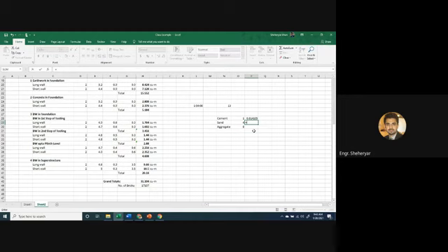Similarly, you have 4 parts out of 13 parts sand, and the total quantity of concrete is 5.184, and the factor for converting the wet quantity into dry quantity, since sand is also taken dry, is to multiply by 1.54. This is the volume of sand. Similarly, the aggregate is 8 parts out of 13 parts. Multiply it with the volume of concrete, which is 5.184, and multiply it with the factor for converting wet to dry quantity 1.54. So these are your volumes of cement, sand and aggregate in cubic meters.